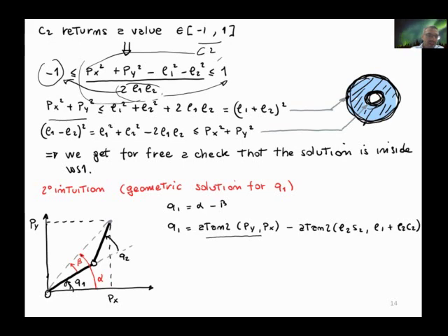We consider the alpha angle: we apply the atan2 to the y component Py and the x component Px of the end effector, and we get the angle solving the arctangent. While for the beta,